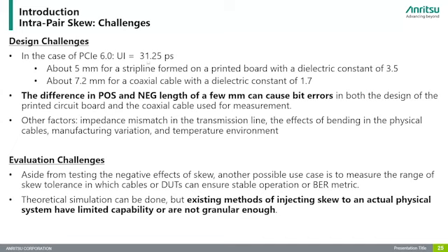That is almost 1/6, almost 18%, 19%. You will lose the phase match with only a 1 millimeter difference, and with a 7 millimeter difference you completely miss one UI. So a few millimeters of skew can cause bit errors. Then it causes a bit error rate, or you lose the skew margin of your DUTs.